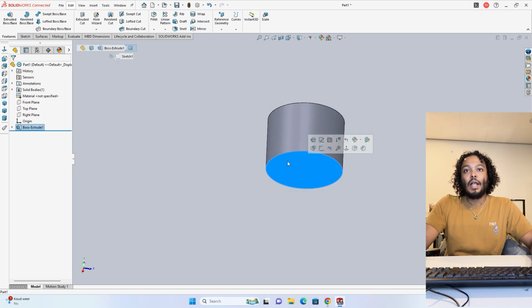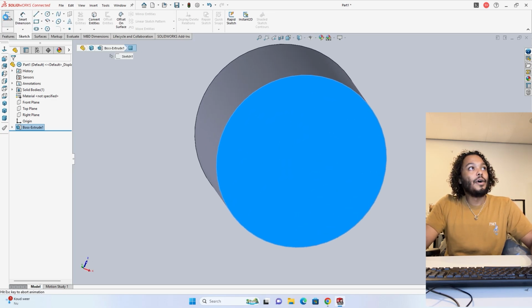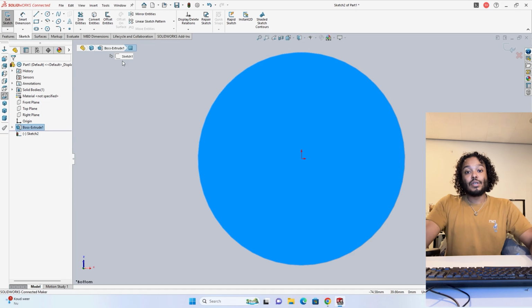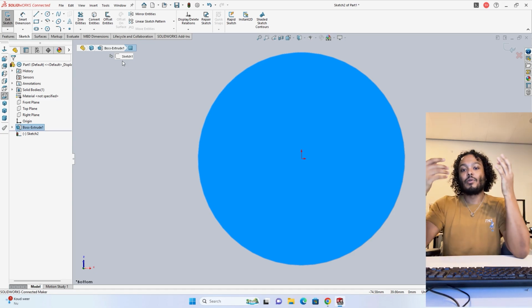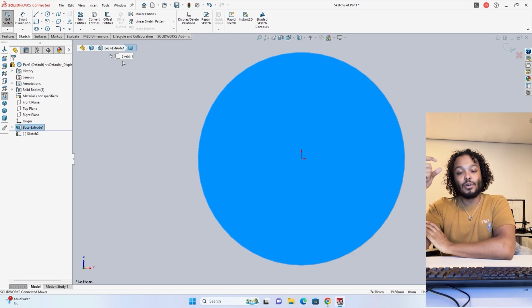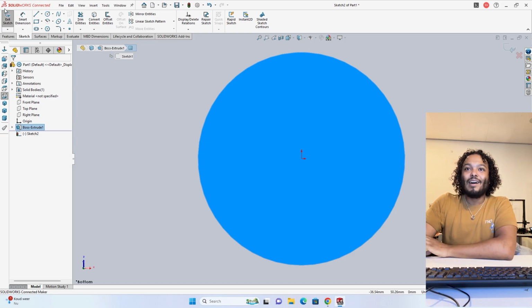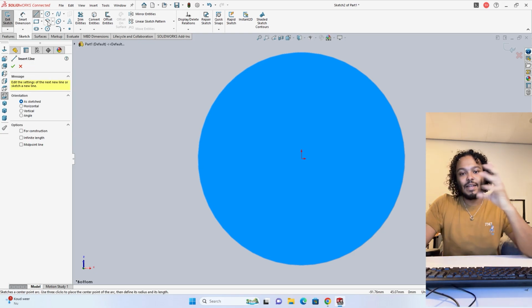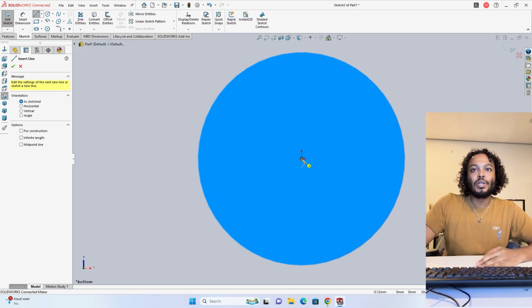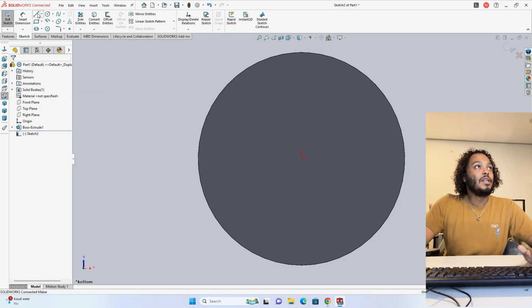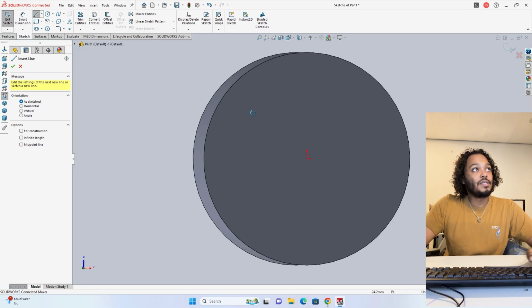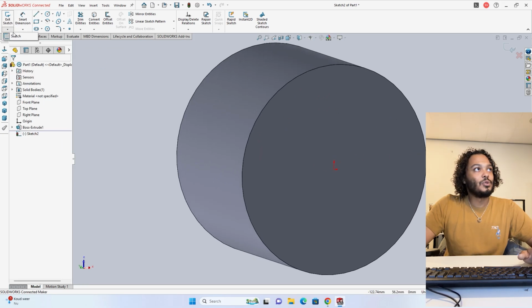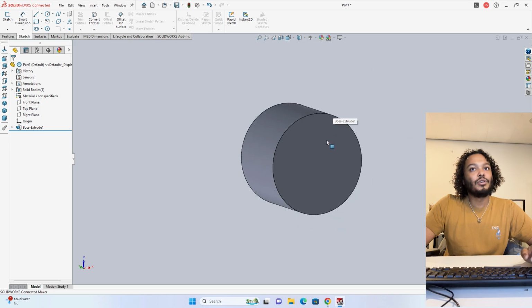So from the bottom, I want to also make a sketch again, because we also need to put a pin right through it. We need to have some surface area where we can drill a hole through it, and then allow us to connect it but still maintain surface area with the cylinder wall and everything. So what I usually end up doing is I take out the sketch tool again, but on this bottom surface. So let me exit it and show you again.